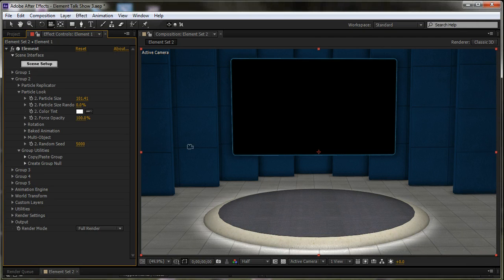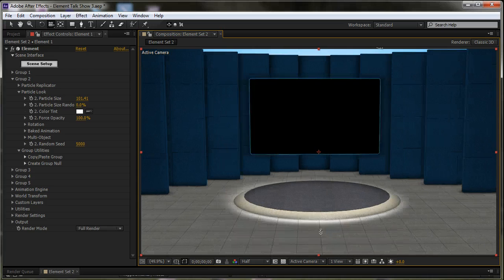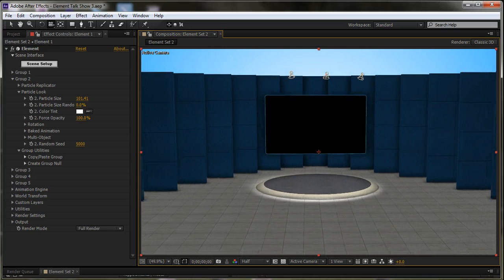In fact, it's the same tile texture that's applied to the panels. The UV repeat on the floor is 20. The UV repeat on the walls is only 5, so you get much bigger tiles that way. The stage that I built is made of two things, and as I go underneath here, let me pull way back here.